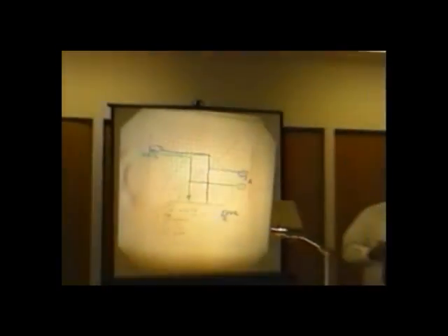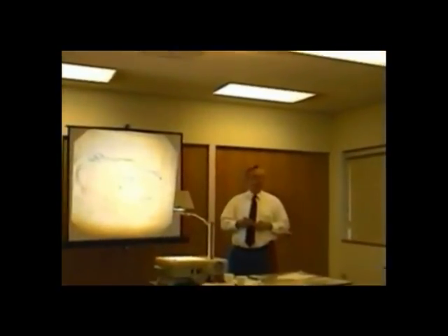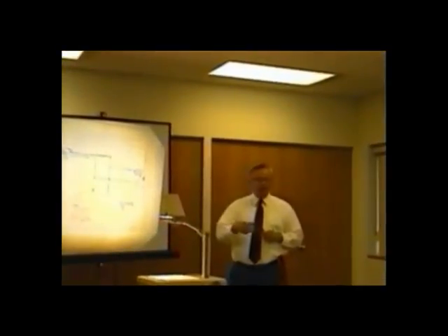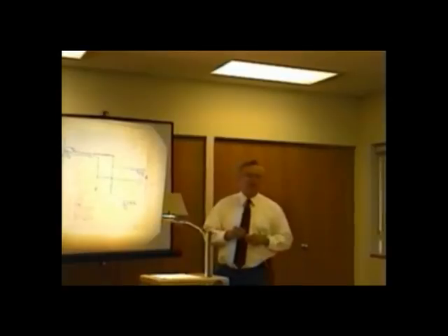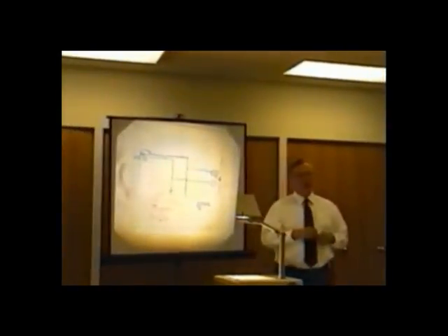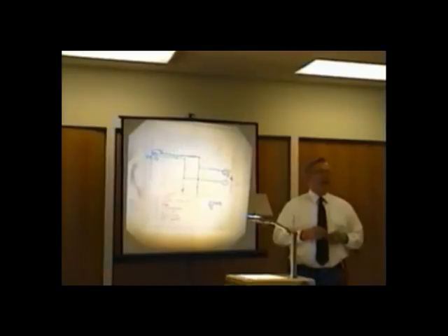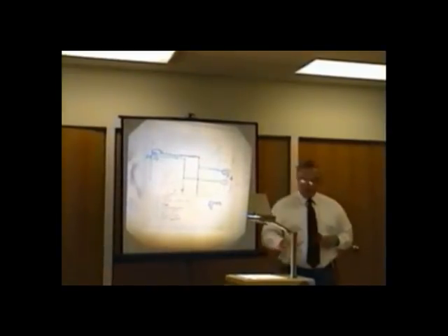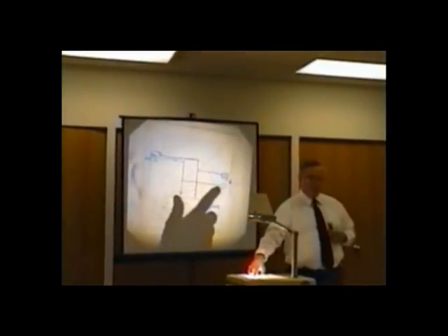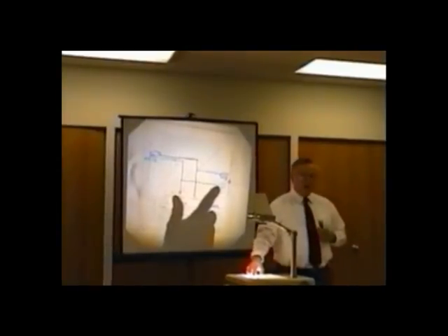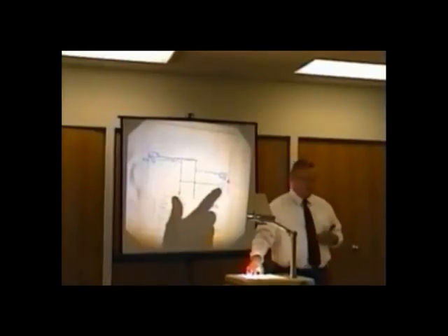Ladies and gentlemen, what cools a compressor? From our days back in school, it's the temperature of the suction gas. And when we undercharge it beyond that 2 ounces, the temperature of the suction gas goes up and the compressor will overheat. Okay? So it's not good. You may run for a while, but you will eventually lose a compressor. You may save electricity for a while, but you lose a compressor.